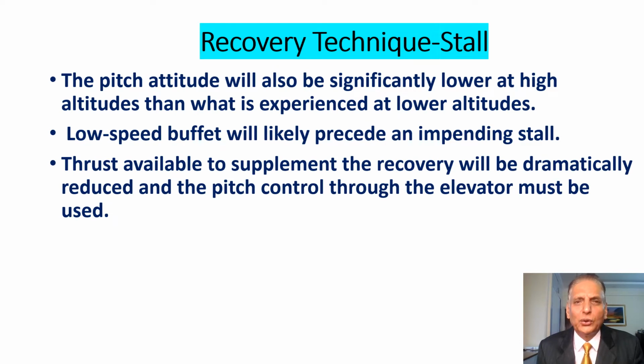The pitch attitude will also be significantly lower at high altitude than what is experienced at lower altitudes. Low speed buffet will likely precede an impending stall. Thrust available to supplement the recovery will be dramatically reduced, and the pitch control through the elevator must be used.